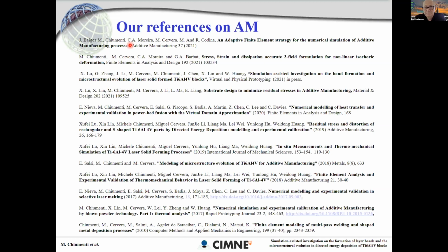And as said before, the coarsening is essential. One important thing that I never said, but I think right now it's important, is that it is very dangerous to refine, coarsen, refine, and coarsen, because this typically destroys the solution.